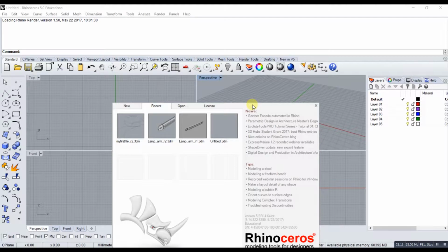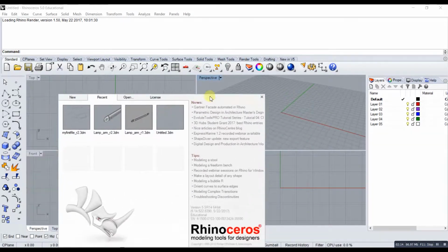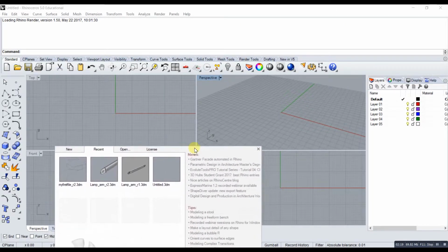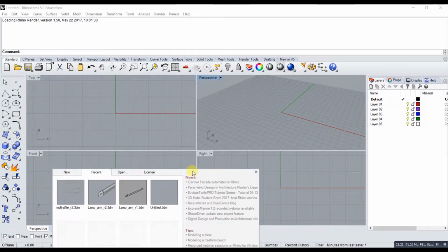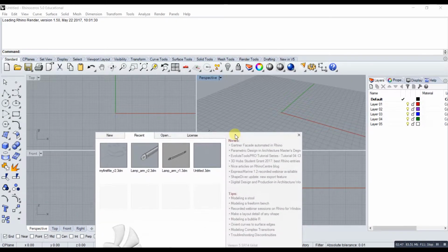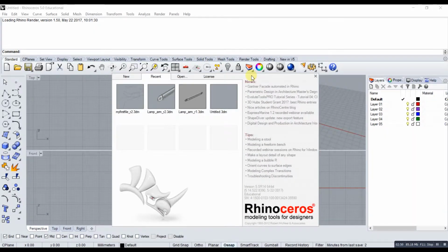So one thing about Rhino is that it will capture whatever settings are set by the previous user and apply them to this new document that you see here in the background. So we definitely don't want to use what comes up there because we have no idea who used the computer before us, right? If you're using a school computer, it could be an architecture student who is making a high-rise building and has it set to feet. Could be some automotive designer who's making a semi-truck. And trying to dismantle whatever settings were set before you got there is a lot more work than just setting up a new file that's clean right out of the gate.